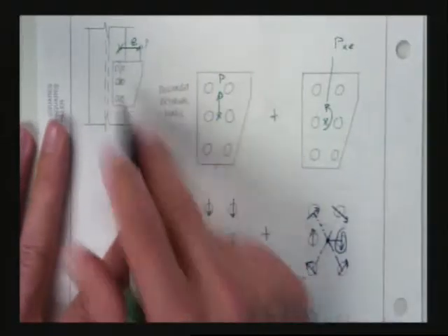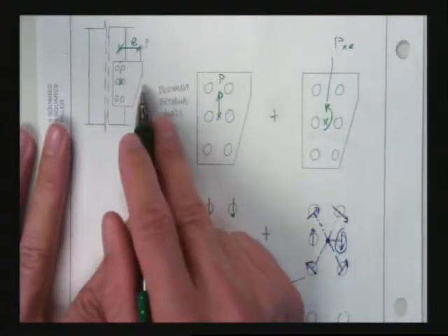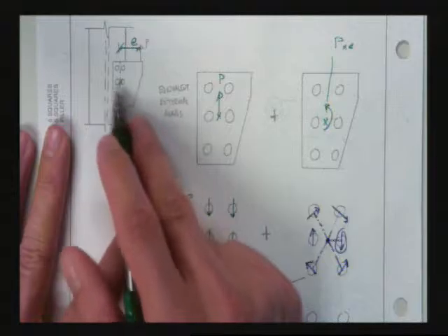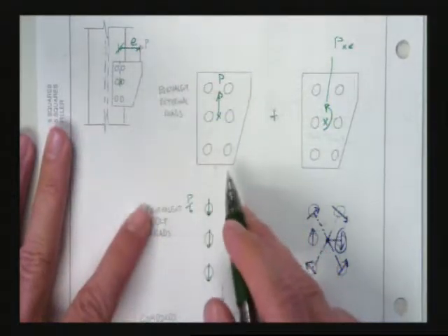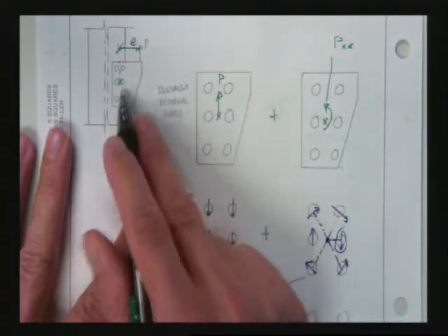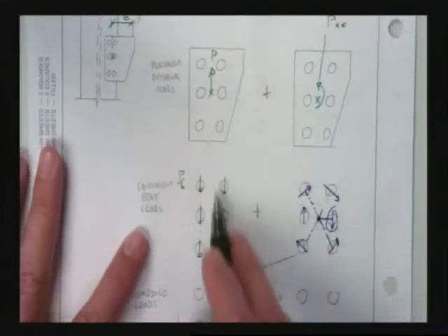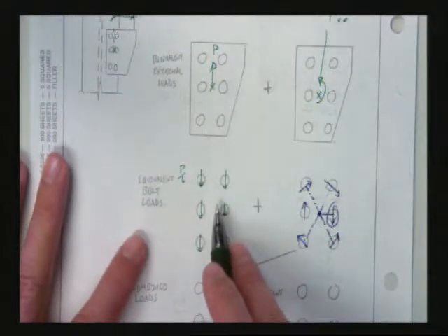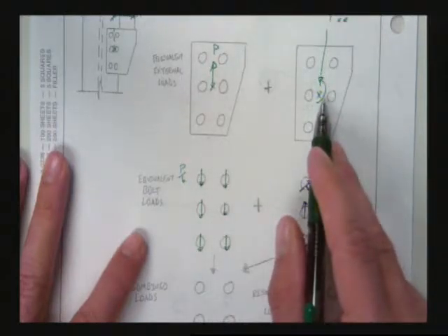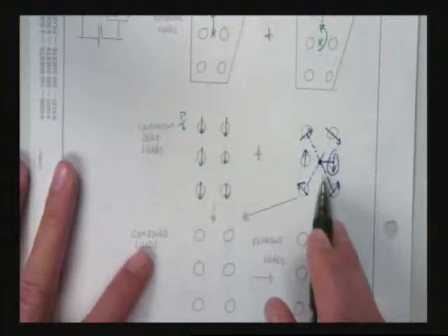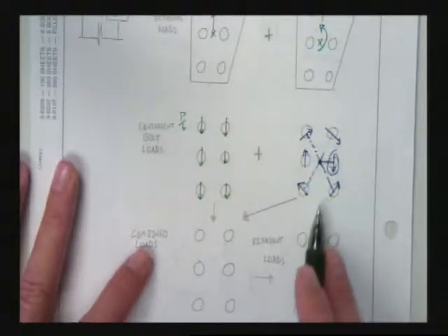So if I move my load, or for whatever reason my center of stiffness was moved because my bolts weren't symmetric, then I'm going to be able to put almost a shear stress on the cross section, and then almost like a torsional stress on the cross section, right? And if I do the torsional stress, I said the stresses would look something like this, right?